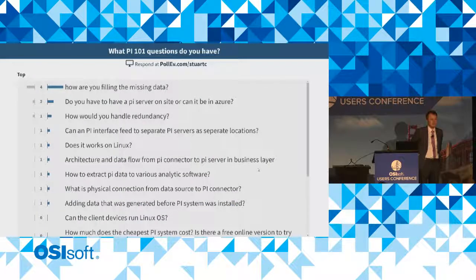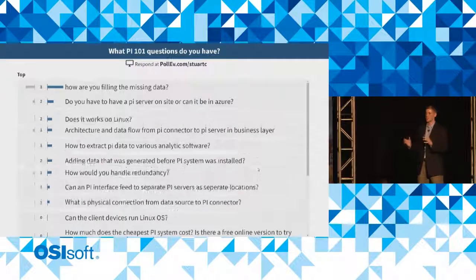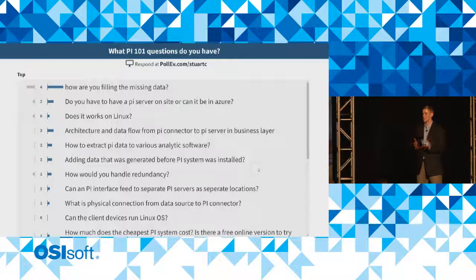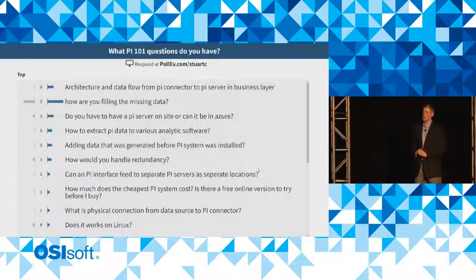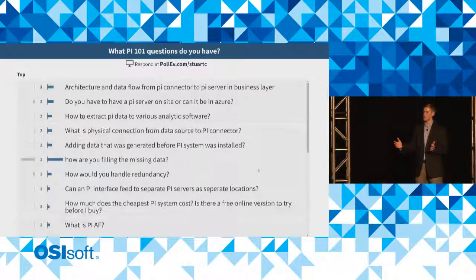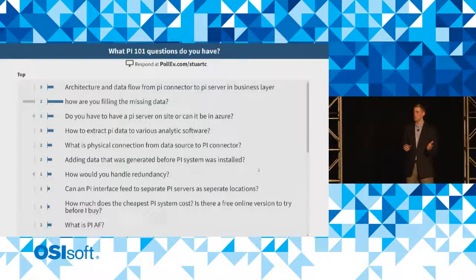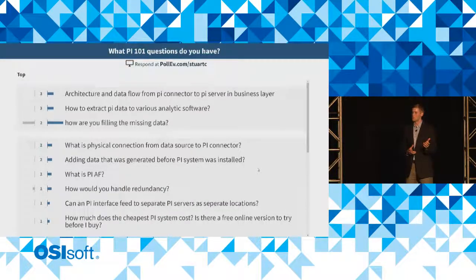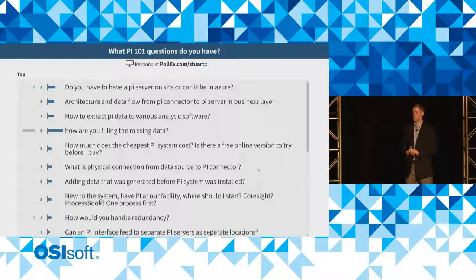Yeah, so the PI system itself isn't going to be able to accurately predict or just shove data in if something's missing. But we have different mechanisms for preventing data loss, everything from high availability down to buffering from our interface nodes, right? We're built and designed to capture time series data, which means if there are network interruptions or connectivity issues between the interface and the PI server, we're going to limit the amount of data, if any data, that gets lost during that translation.